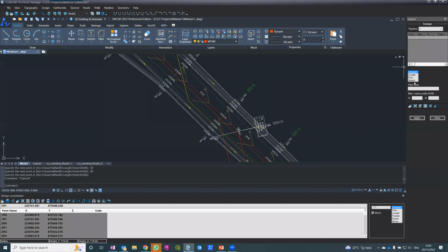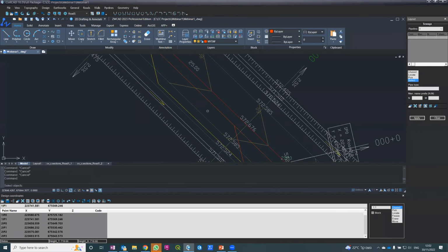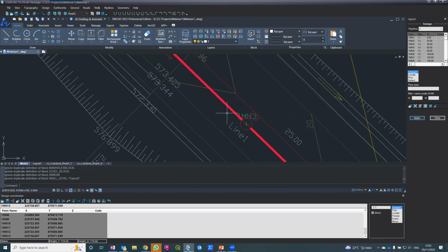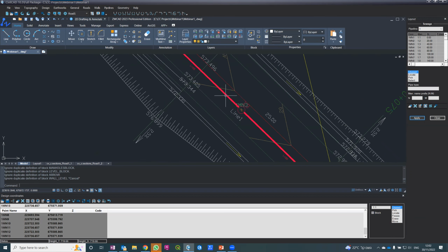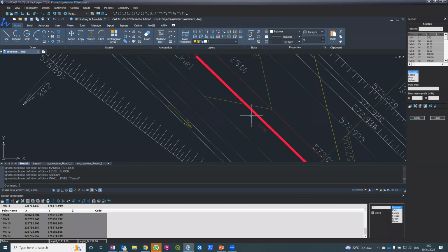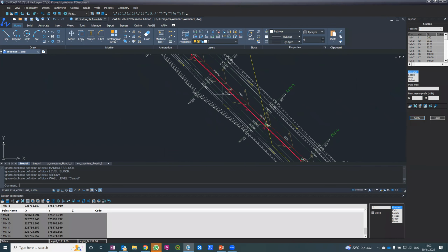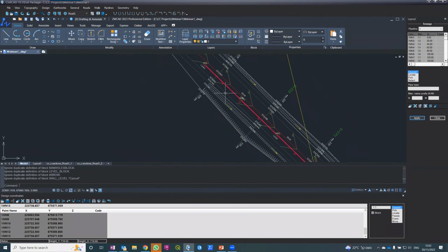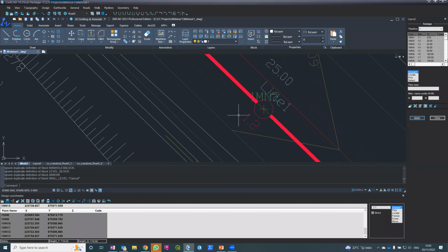So let me select it. This will be practically the same as what I did in the road. I'm taking this polyline, select it, and automatically the software converts it into a pipeline. So you can see here, this is the pipeline. What do I see? I see the pipeline, I see the length between segments. We know it's 20 meters. I see that the software gave it running numbers. This is line number 1, and it also created the coordinates here, which I can freeze for now because it's overlapping and I don't need it.